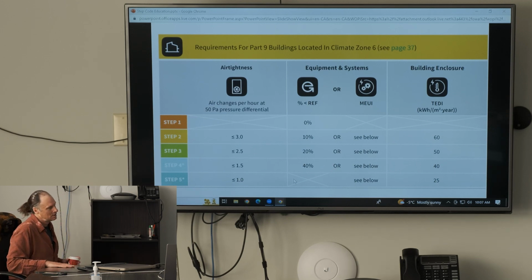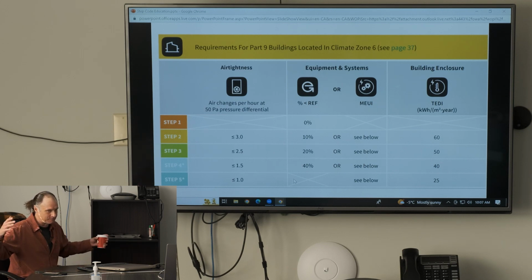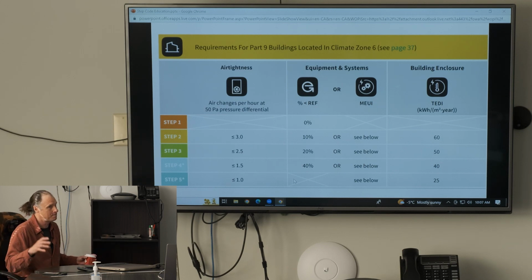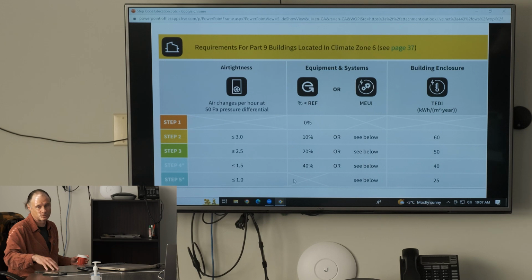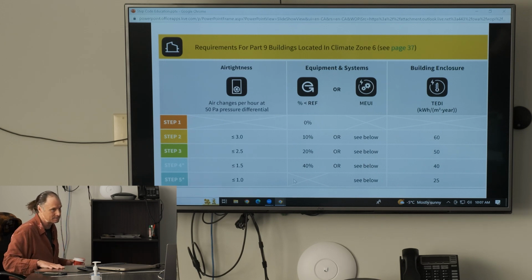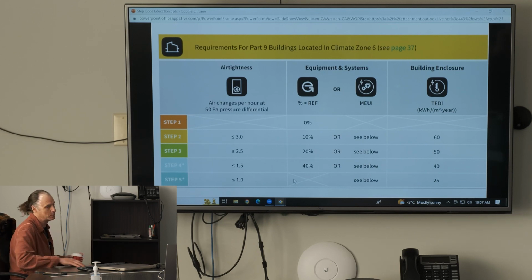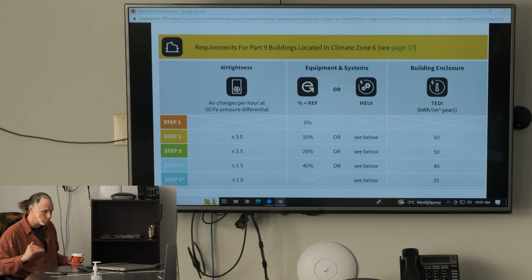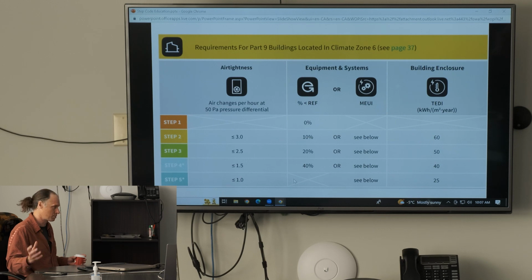And so, when the building is fully constructed and all the mechanical equipment is installed, there is going to be an air test done. And it will take into account all those penetrations that have been created by installing these systems. And if they're installed properly and well sealed, then air leakage shouldn't be a huge issue. And so when you have a really low air leakage rate, then you want those mechanical systems to be working to bring in that fresh air.